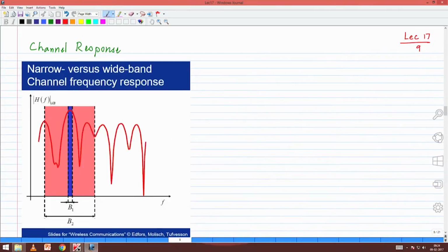Okay, so now I have a channel which has got lots of multipath, and I have a certain frequency response that is given by the red signal. My GSM signal has got 200 kilohertz only. Therefore, its resolvability is very less. And let us assume it is such that the resolvability of a GSM multipath says there's only one tap. That's because of the resolvability. So the GSM channel sees a single tap channel, which means in the frequency response it is going to be flat. Am I right? And that is what we are showing here.